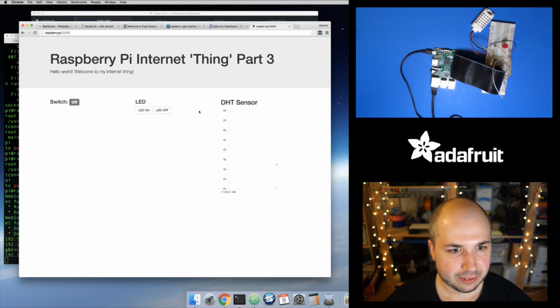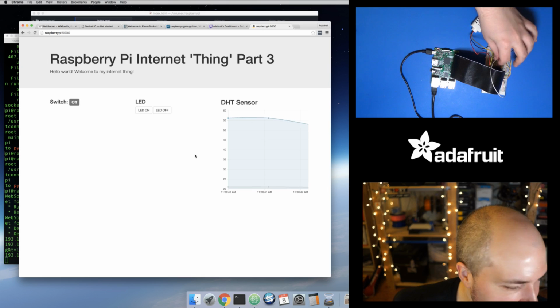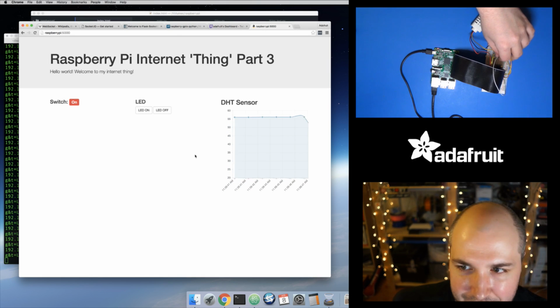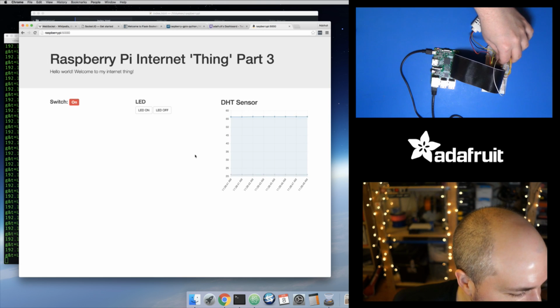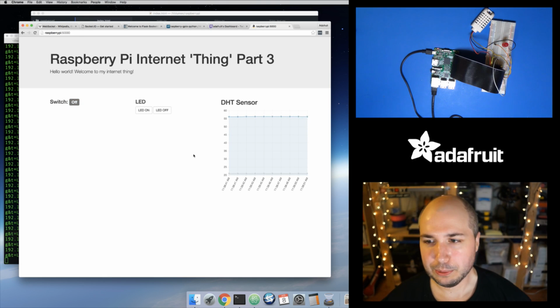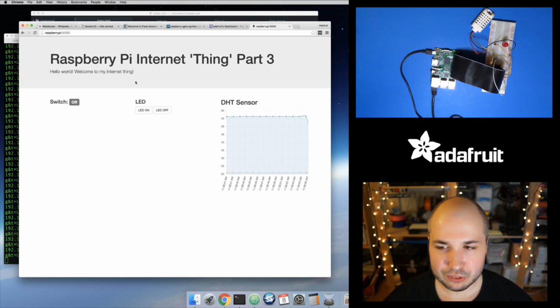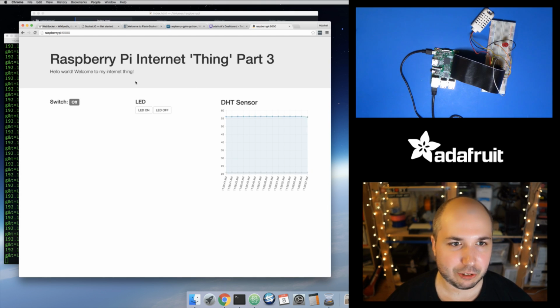Now I go to localhost. And now the big test. Let's see if I move the switch. Oh, now you can see it's toggling, and now it's on, and now I toggle it back, and now it's off. So that's cool. So now we're using socket.io basically to receive that switch. So as soon as the switch changes, that change is pushed out.